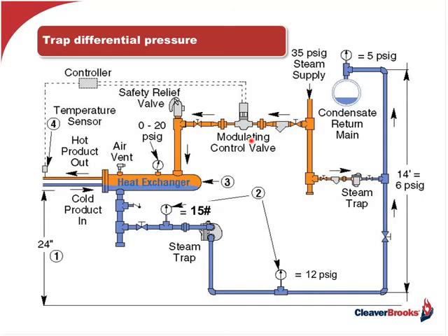I'll tell you, I would be reluctant to say that they had to be rebuilt every year. But certainly a good, diligent trap testing program should be put in place. And that starts with an inventory of where your traps are. And then those should be tested. Normally what we're finding today is you can shoot them with an infrared gun, and you can see the difference in temperature on the upstream versus downstream side of the trap. That'll tell you something whether or not it's leaking through and needs to be rebuilt or replaced. But ultrasonically is probably the best way to test those traps.